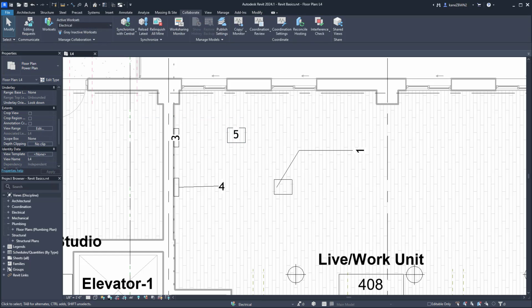I've got one other thing to show you related to worksets, but it requires closing the project. And before we do that, we need to synchronize the changes we've made with the central model. To do that, you can run the Synchronize command on the Collaborate ribbon, or you can click this cube on the bottom toolbar.